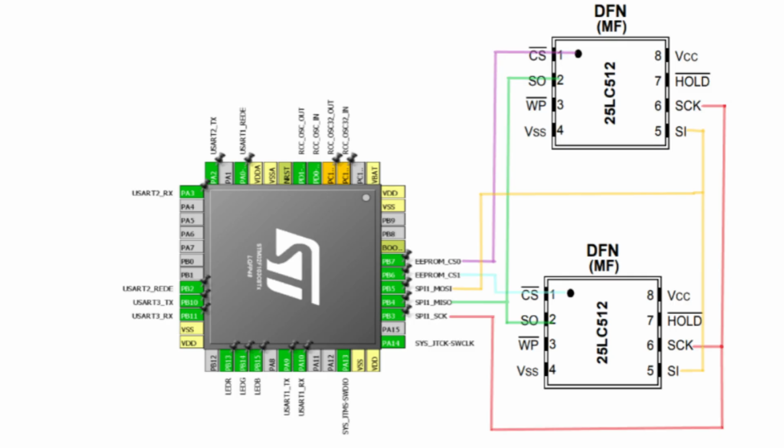Third, decoupling capacitors, absolutely essential. Place a small ceramic cap, 0.1 uF or 0.01 uF, physically close to the VCC pin of every single chip on the SPI bus, master and slaves.